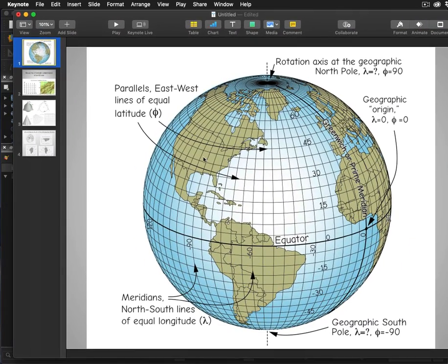So most of us are familiar with this latitude and longitude coordinate system. Lines of equal longitude go in the north-south direction. This is the prime meridian, the 0 longitude. And as I go in this direction, I get these negative longitudes. We're at about minus 90 longitude here in Minnesota. The latitudes increase as I go north: 0, 15, 30, 45. We're pretty close to 45 degrees north. So we're here at 90 west, or minus 90 degrees, and 45 north, or plus 45 latitude.